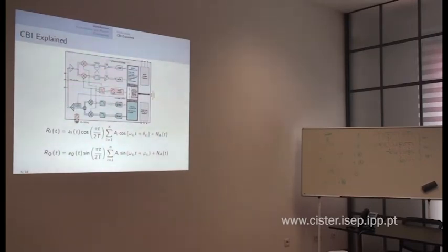So we are here. What will happen is that because this amplitude will depress, we have some noise here, and at those instants of time, the information that is being conveyed cannot be received. Now, if that signal does not depress so much, and we still have a reasonable signal-to-noise ratio, then this demodulator will in principle be able to decode this information, or maybe it will decode it partially, and there will be errors. And that we want to study now.